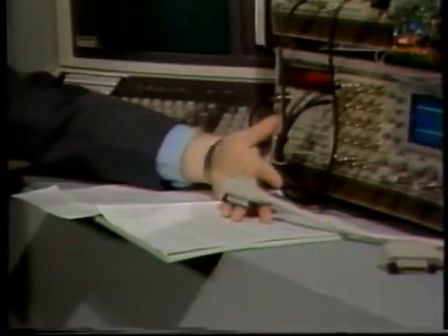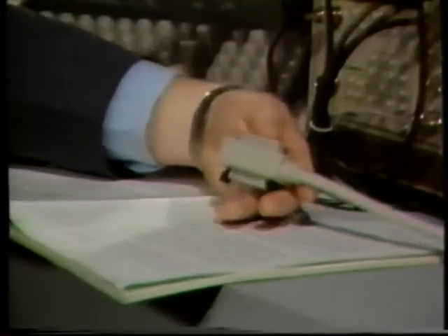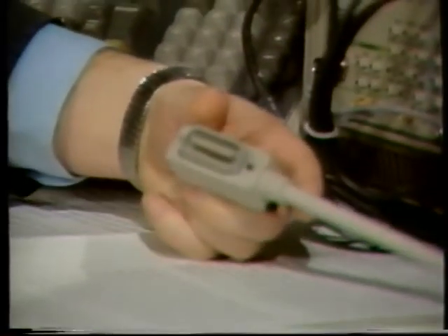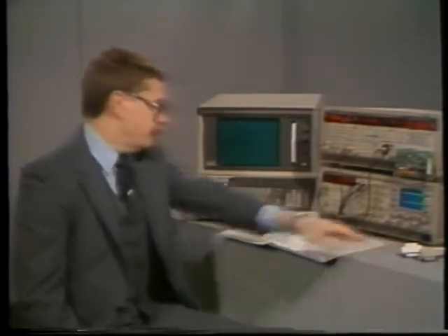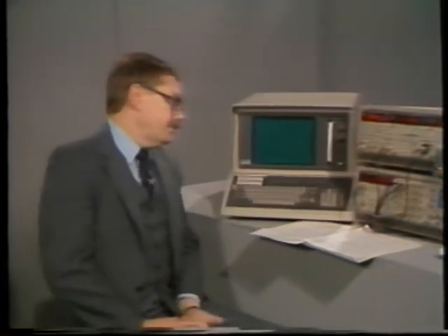The connectors can be stacked to interconnect multiple devices as you wish. The maximum total cable length can be up to 20 meters with at least one standard device connected per 2 meters of cable. 15 devices are the maximum for the bus, one of those normally being the controller. At least 2/3 of those must be powered up at any given time. Each device has a unique address on the bus between 1 and 31. Normally that is set by switches on the rear or inside the instrument itself.